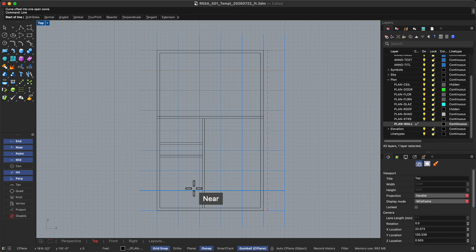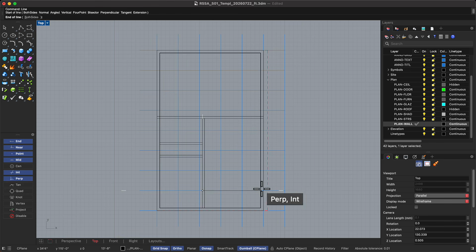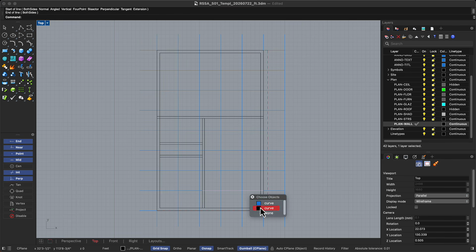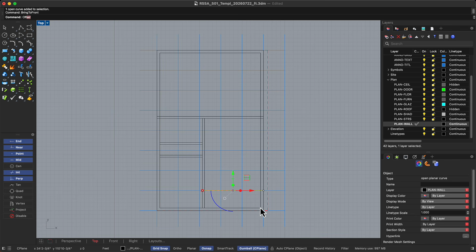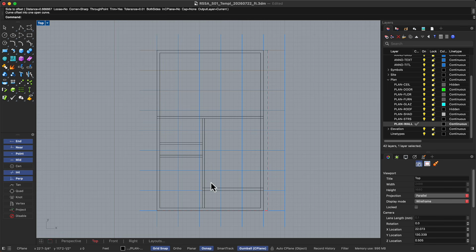On the south side, recess the bedroom wall by 5 feet to the grid and have it create a small patio. The recess gives the bedroom a more protected connection to the outdoors, and when combined with a future roof overhang, can help manage direct solar gain on the south side.